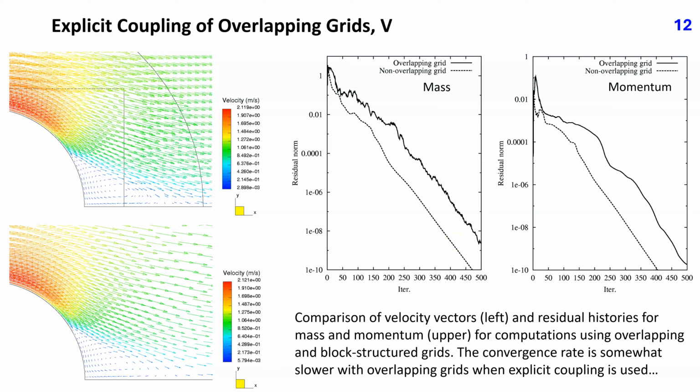Variable values at overlapping boundaries are updated after each outer iteration. Convergence rate would probably be somewhat faster if the update of boundary values was performed after each inner iteration within the solver of linear algebraic equations. However, this would require significant programming effort. Here, one complete outer iteration of the SIMPLE algorithm is performed on each grid in a sequence until convergence criterion is satisfied. Residuals were reduced 10 orders of magnitude and no convergence problems were encountered.